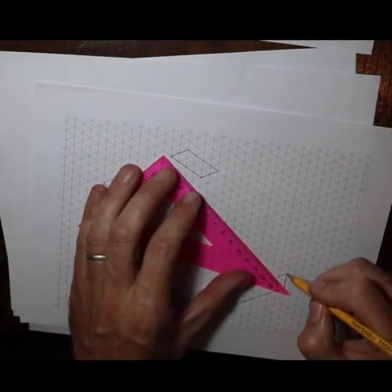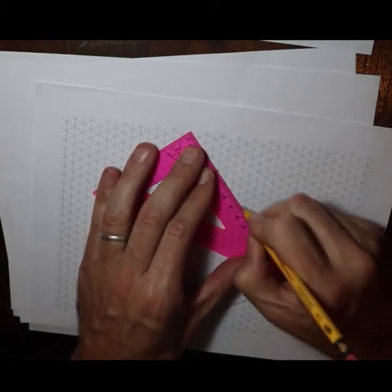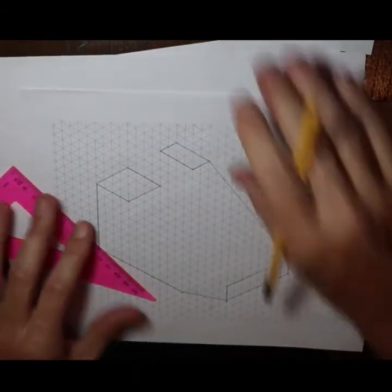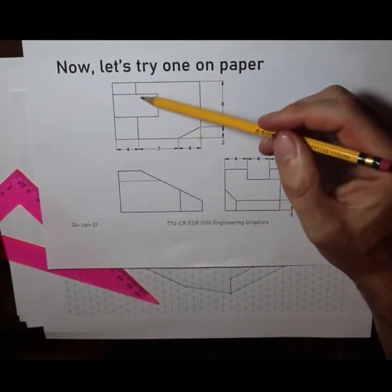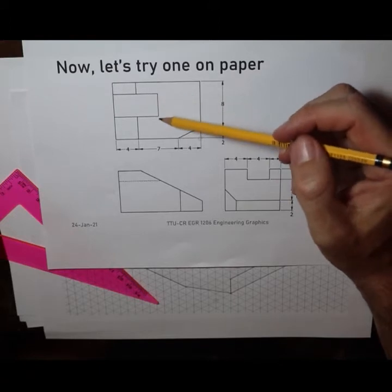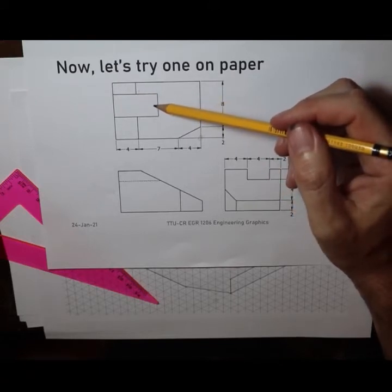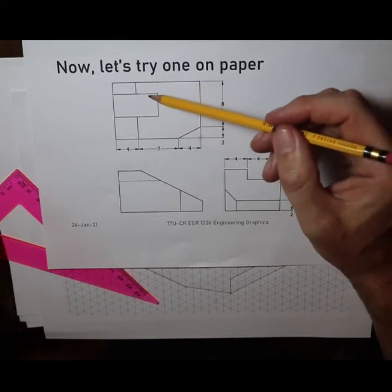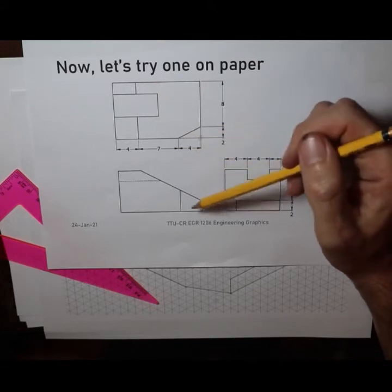And that's going to be one of our main lines that we need to be using. Right, so we have this edge. Now, we can use what we learned earlier, right? We can construct where this location is, because there's no dimension on it, because it depends on the slope here. So we know that this line and this line are parallel in this drawing, so they have to be parallel in our drawing as well, right?